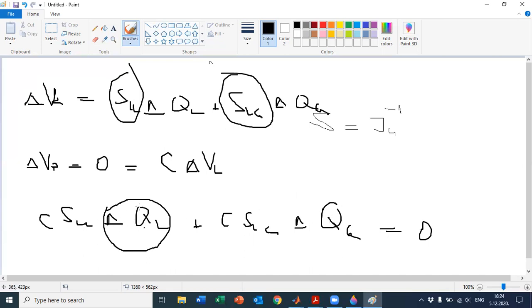When a reactive power change in the network occurs, the changes of the voltages in the network also occur. To smooth out these changes and remove these voltage deviations across the network, the generators need to be operated in a manner which follows from this equation.